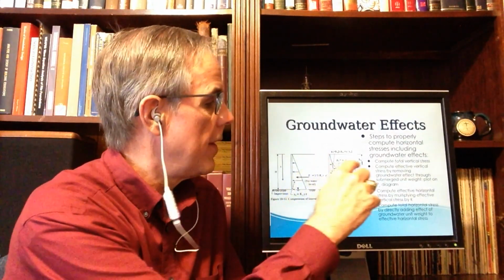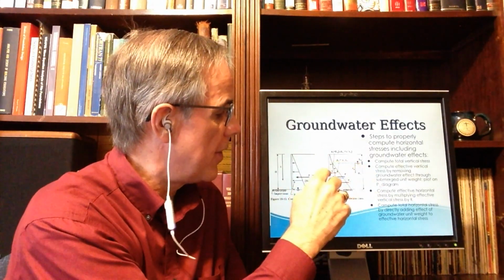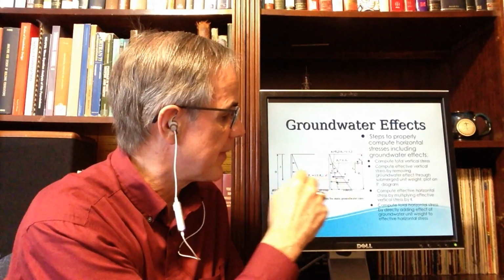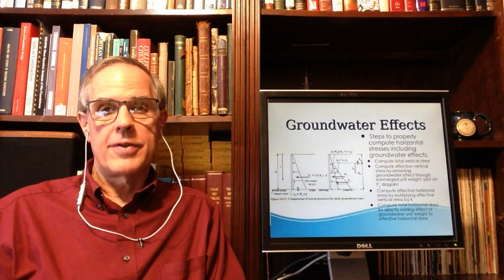For example, if your water level is up here on this side of the wall, and on the dredge side it's like that, if you've got a gap there, then you know you have an unbalanced hydrostatic force and you take it into consideration.